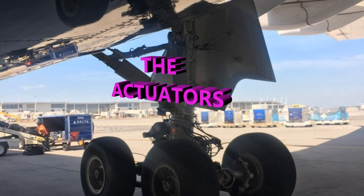The hydraulic connection enables a crossover when the actuator reaches a full retracted position. So that's the mechanism going on. There's a minimum torque coming from the actuator. Again, there are certain degrees. It's just to make sure you have a certain travel and it's not going past a certain number of degrees. In this case, we're talking about 72 degrees.